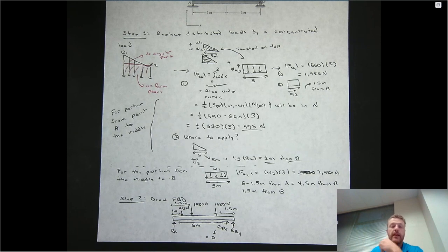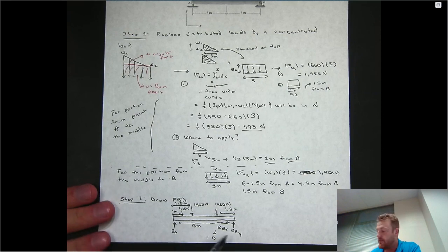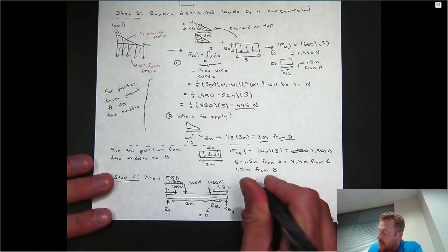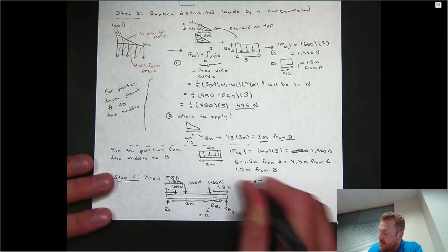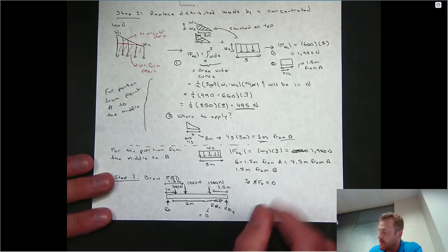In general, you want to pick whatever equations of equilibrium are easier in order to let you solve for, most easily, the 3 unknowns of interest. So in this case, they are the horizontal RBX, RBY, and RA. So the 3 that I'm going to choose to enforce, and you'll see why in a minute, are I'm going to sum all forces in the x direction and say those have to be equal to 0. And I'm going to have horizontal right be the positive there.